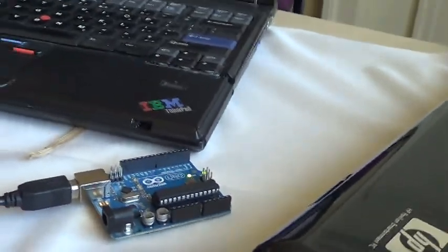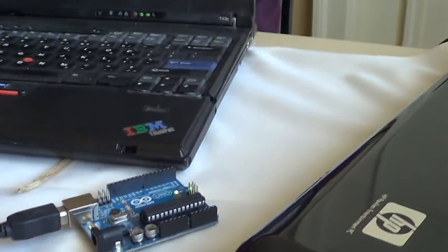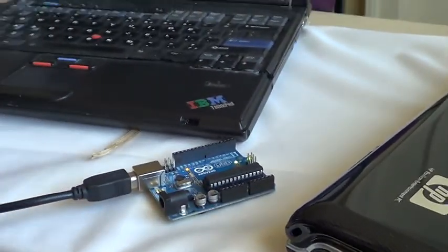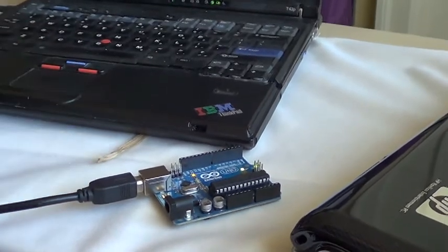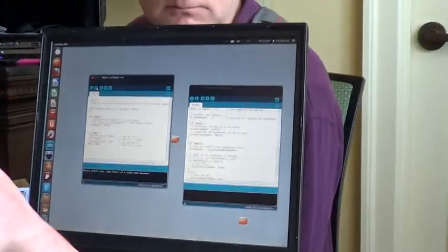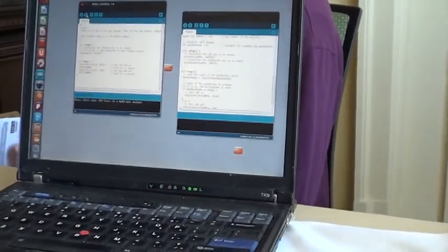Okay, so it's doing it by some kind of name. It knows it as Arduino. It treats it as a COM port or something like that. And basically, this is a USB to serial converter in there. So it looks like a serial port to the computer, and the computer just sends data to the board, and the board's like, oh, this is my data. Oh, okay. Okay, so the next step was something about... Yeah, so if you wanna, these switches are pretty simple.